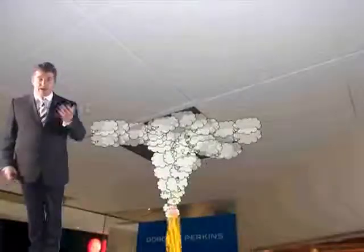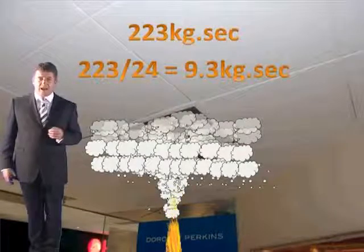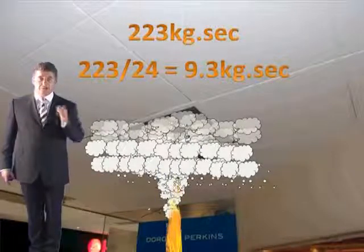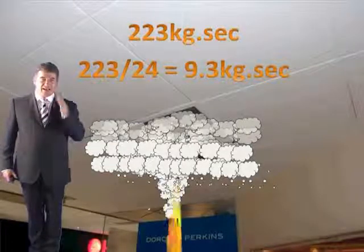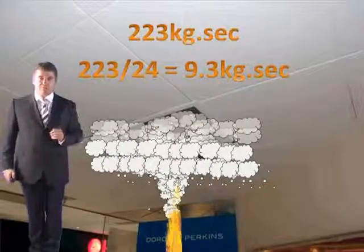So what you need to do is work out what your mass flow rate was, which we had earlier, and divide that by the number of ventilators that are extracting. Now our mass flow rate of smoke was 223 kilograms a second. If you divide that out by 24, you've got 9.3 kilograms a second per ventilator. That's how much will be going out. We've got an mcrit much higher than that, so in this case it does satisfy the plug holing check. It's very unlikely to plug hole.